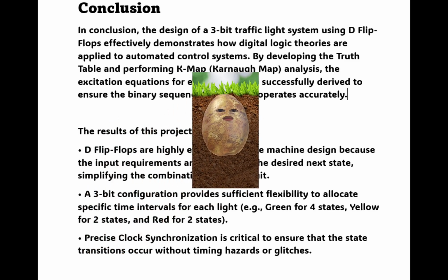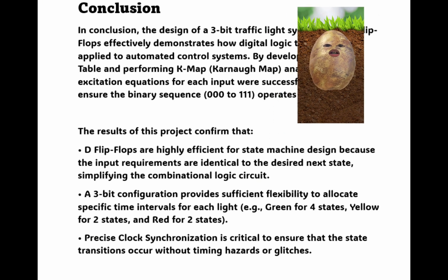The result of the project confirmed that flip-flops are highly efficient for state machine design because the input requirements are identical to the desired next state, simplifying the combinational logic circuit. A 3-bit configuration provides sufficient flexibility to allocate specific time intervals for each leg. Example given: green for 4 states, yellow for 2 states, and red for 2 states.